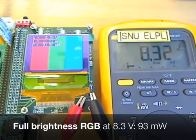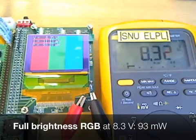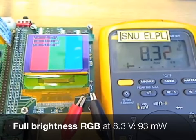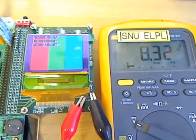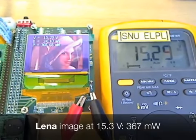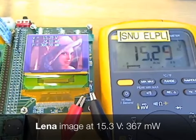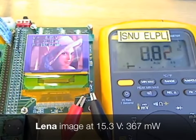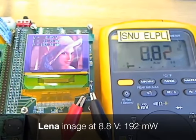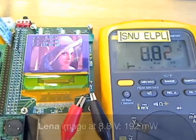Now I change the color data with full brightness and lower the supply voltage to 8.3 volts. It consumes about 93 milliwatts. As we can see, the brightness is close to the half brightness image with maximum voltage, and the power consumption is reduced to 1/3 compared to the maximum voltage case. Now, let's look at the natural images. This is the famous Lena image with the maximum supply voltage, and this is the modified image with 8.8 volts. We can reduce the power consumption from 367 milliwatts to 192 milliwatts with a small image distortion.